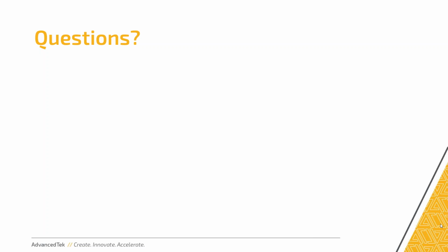So these designs for additive are taken into account right away from the beginning. They're looking at the functionality of the part. What does my part do, and how can I use the benefits of additive to add value to this? That's when they're using the generative design software. That's when they're starting to get some ideas of shapes, and that's when they're looking at kind of optimizing it. All right, what way do I want to build it? How do I want to orient it? Are my supports going to be on an outside surface that are going to be easy to clean up?